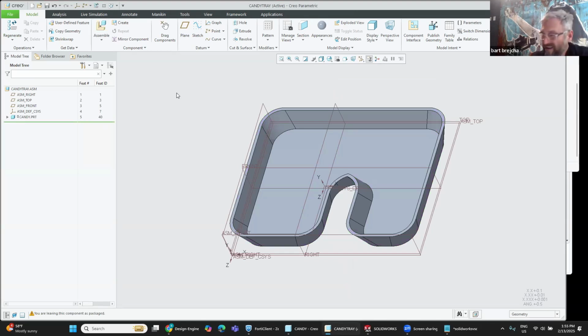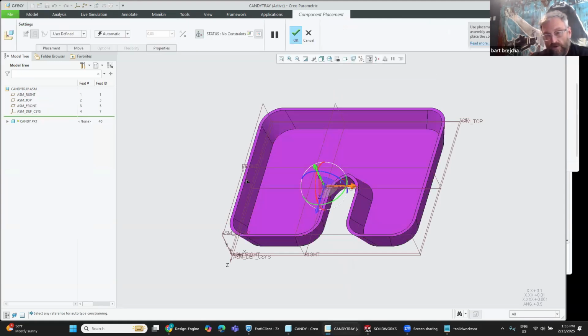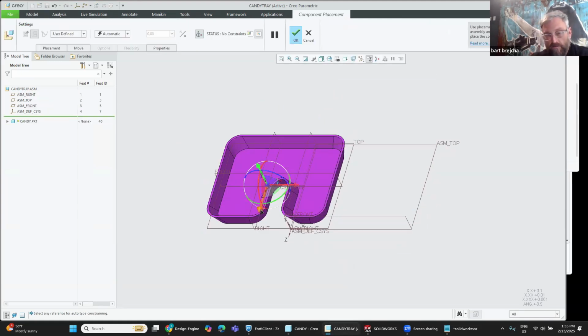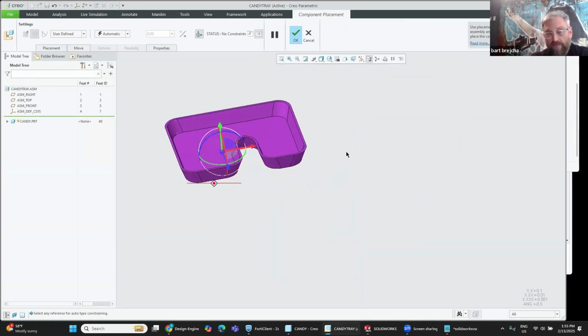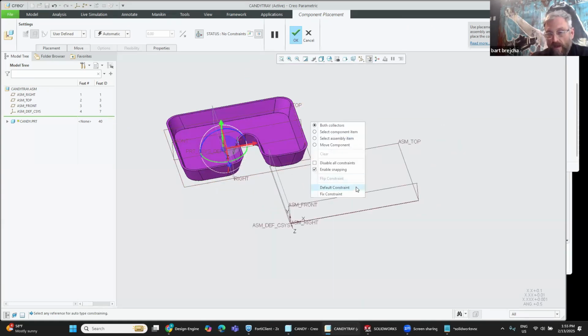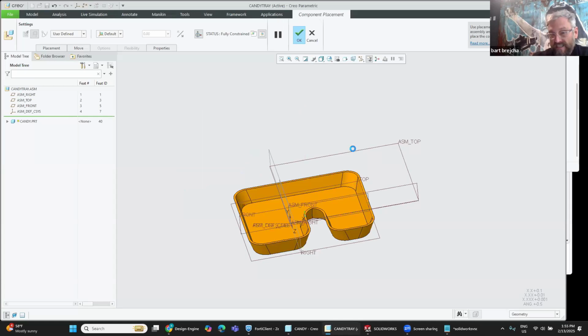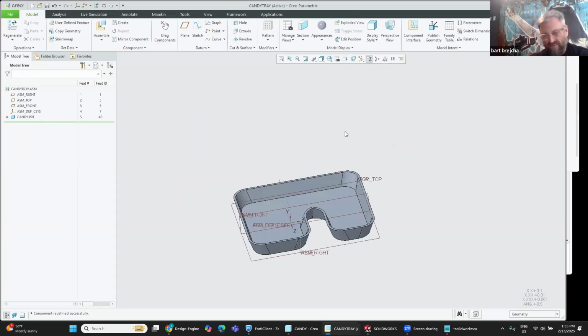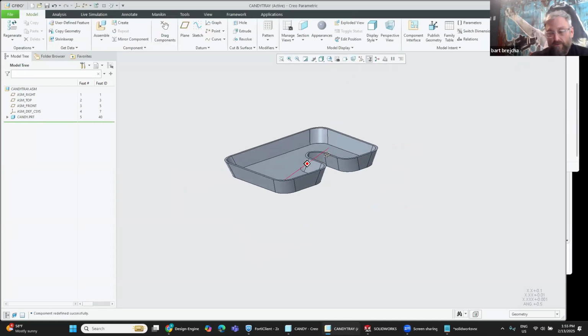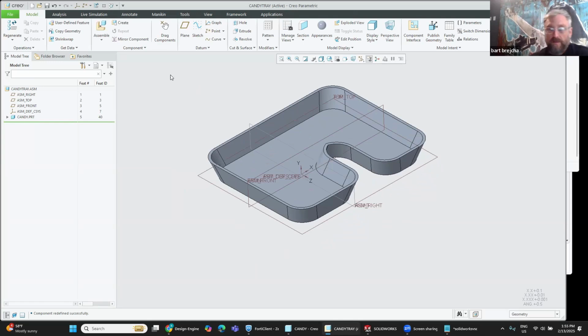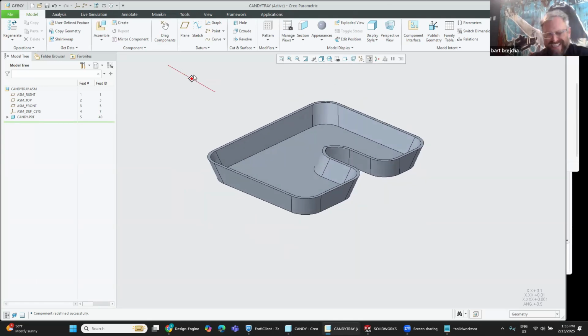SolidWorks puts an F. Not one person I've ever seen cares. The difference is SolidWorks happens to put it frozen at the default coordinate system. I particularly need to see it locked to the default coordinate system. A slight difference between the typical ME, who should rather have anxiety if it's floating, right?